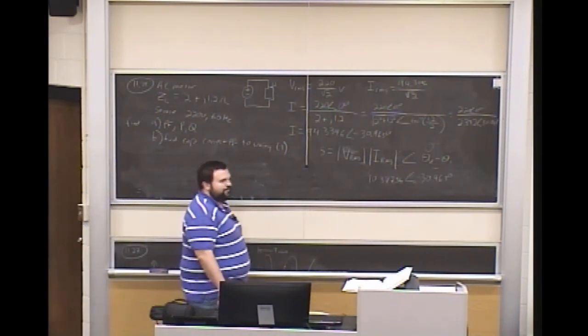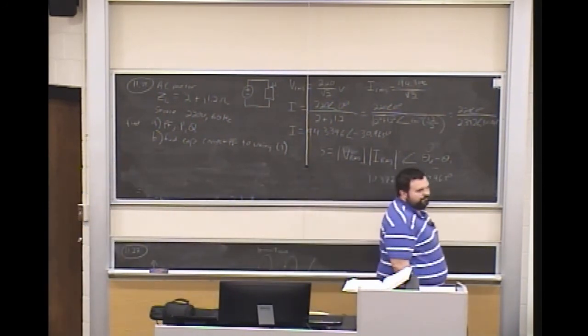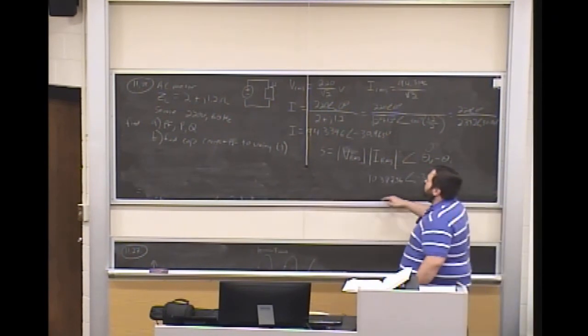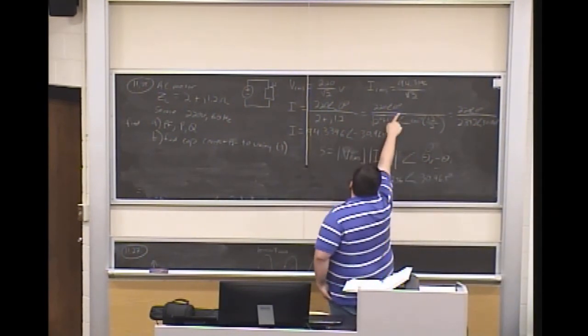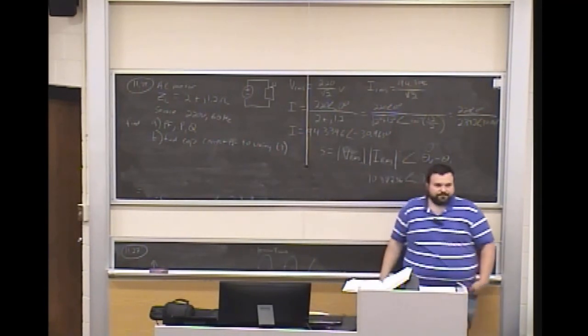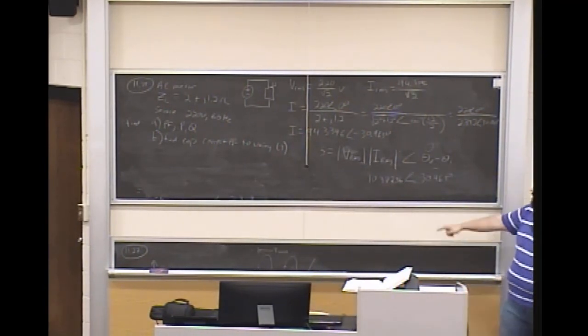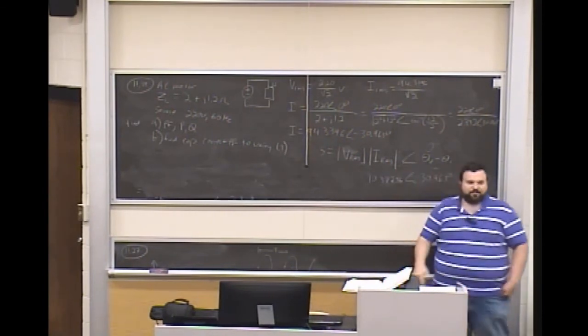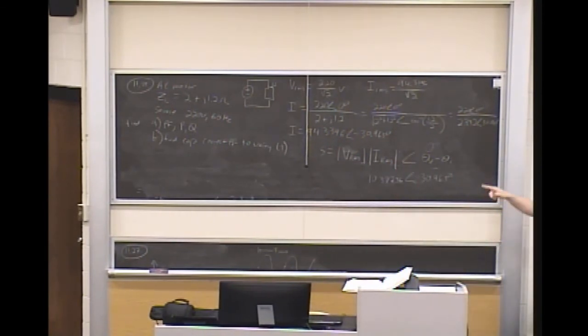Griffin: So wait, where do your VRMS and IRMS come from? The IRMS is the 94.3396, right? Mm-hmm. And then which one is the VRMS? Or sorry, it's the 94.3396 divided by root 2. Okay. So this 94.3396, if I were to do that in the time domain, that's my amplitude. I just divide that by the square root of 2. That gets my RMS value. Okay. Allie, did you have a question?